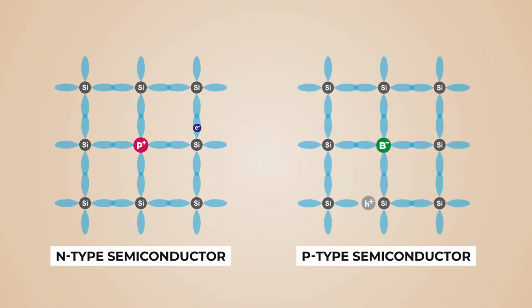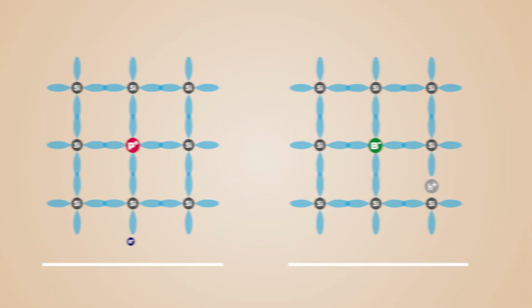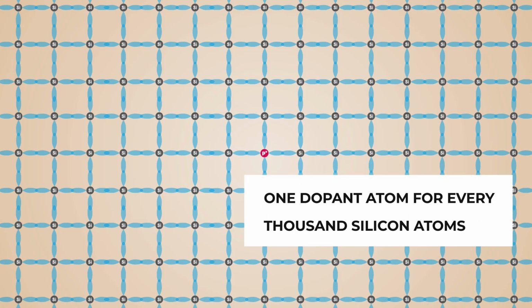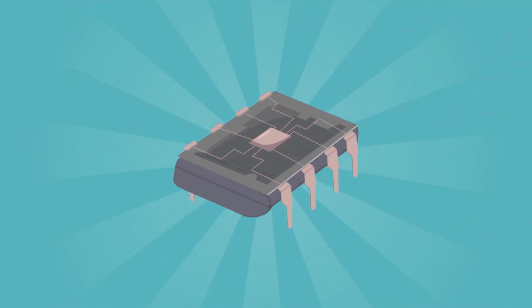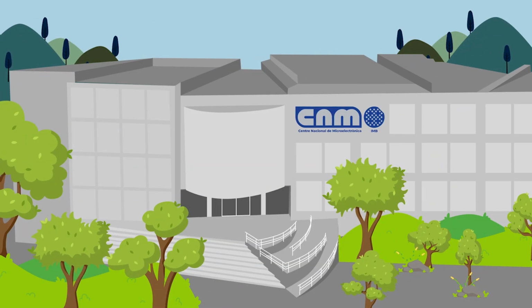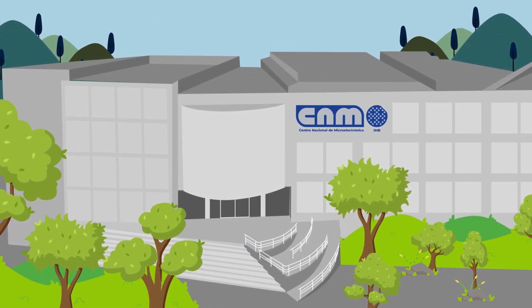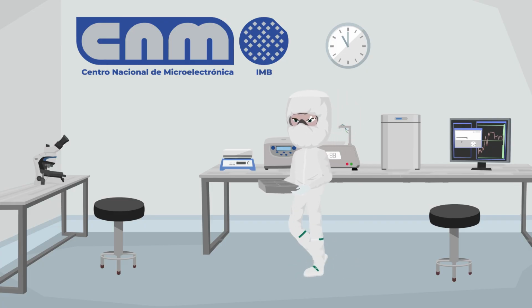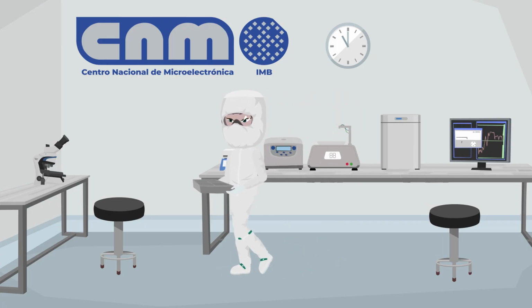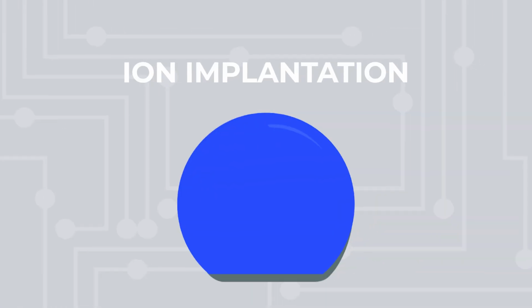The atoms we add are known as impurities, since they make the material no longer pure silicon. After doping, there is about one dopant atom for every 1,000 silicon atoms. But how do we actually introduce these impurities into semiconductors? Doping is one more processing step in the fabrication of electronic devices and is carried out inside a clean room, which is an environment with controlled conditions and extremely low levels of particles. The most common technique is called ion implantation.